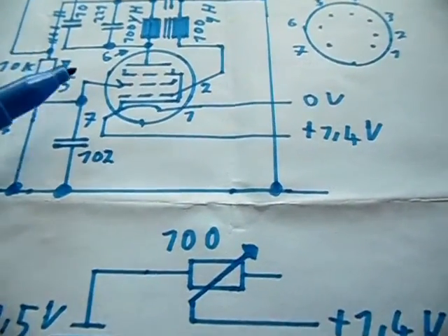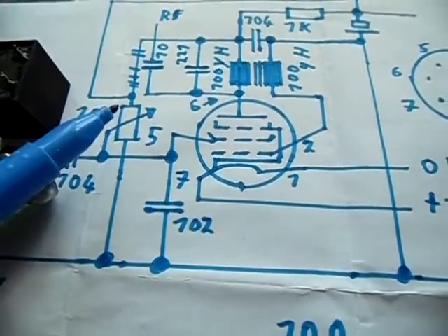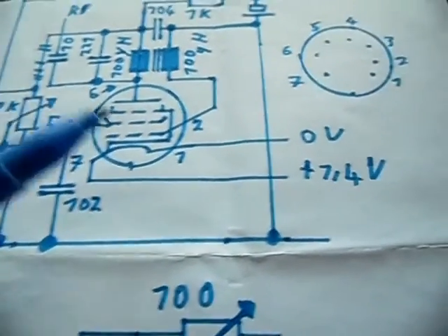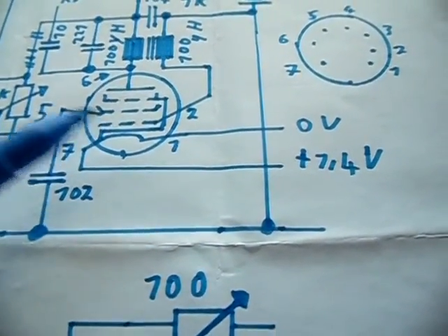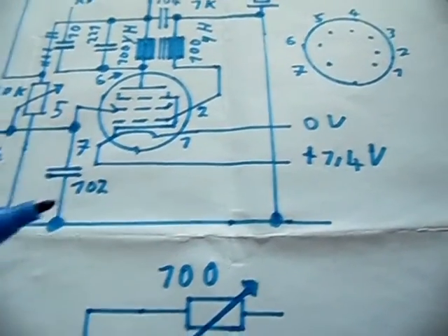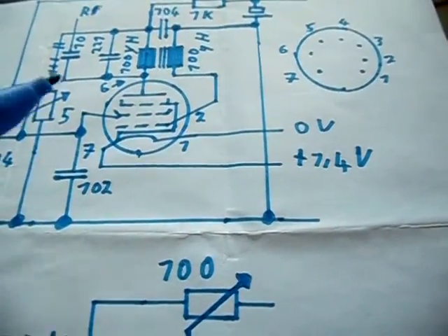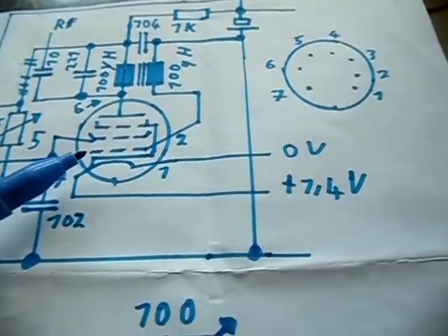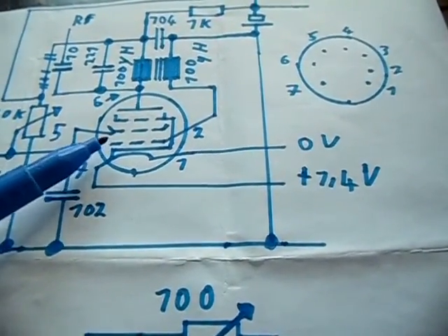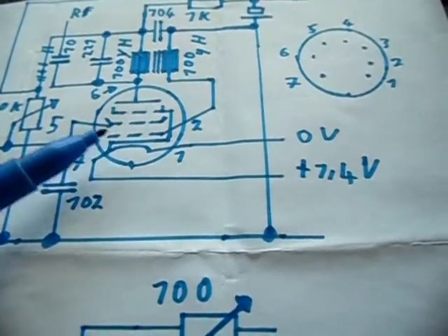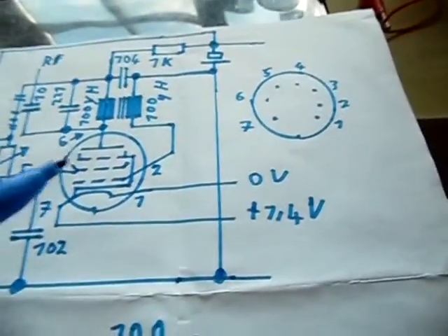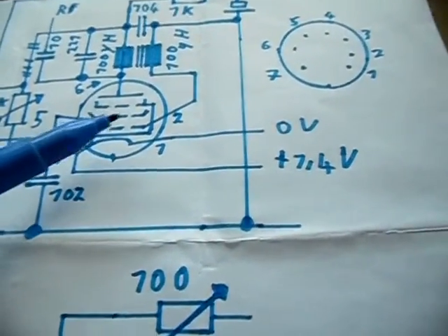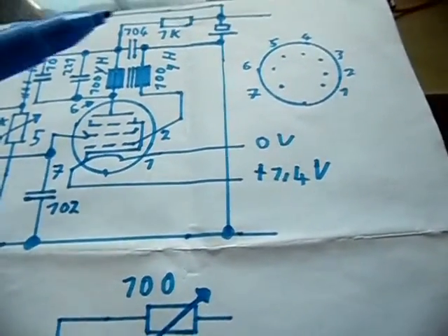So you can connect, for example, the second grid to a potentiometer, so you can dim the LED. The first grid needs to see a negative voltage, so you want to connect it to ground via a resistor. Do not connect the first grid to B+. It can work, but I was told that the first grid is very close to the cathode, and so if you connect it to B+, it can arc over internally, and eventually the tube can get destroyed. So you want to connect the last grid to ground.